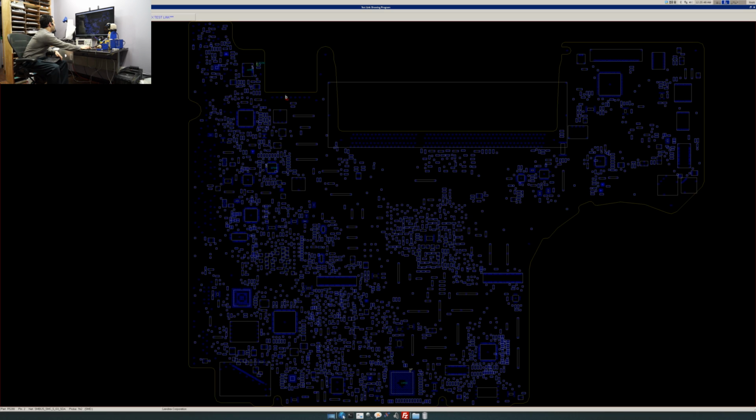Then in the upper left corner, you have the battery indicator. It goes to the battery indicator. Obviously, the battery indicator, in order to know what the battery is doing, should be attached to the data line that's going to the battery. You have it going to the battery charger chip, the U7000, a little bit lower than that, and then below and to the right, you have it going to the third upper right ball on the SMC, which is U4900.